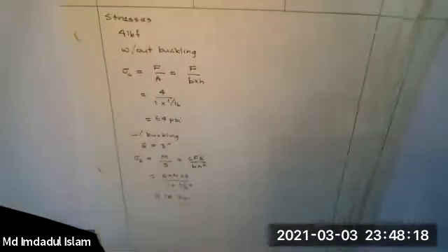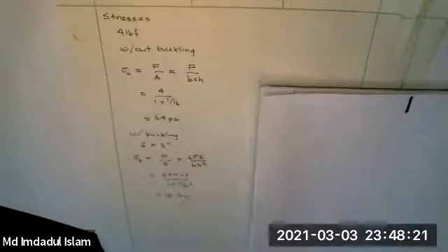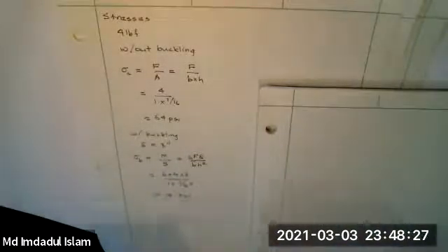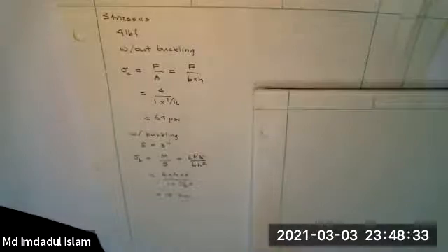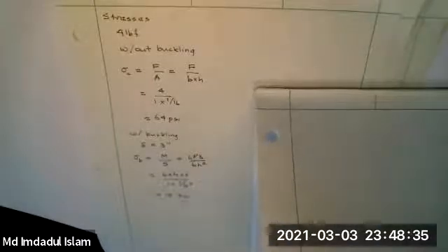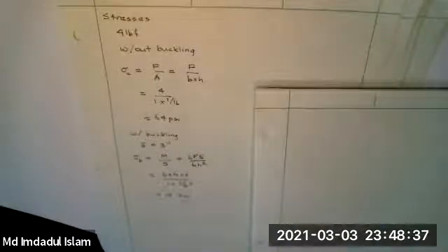Let me do a different situation. We can expect that these buckling loads are going to depend on what you do on the ends. If you let them rotate on both ends, then that'll promote buckling, that'll help buckling. If we clamp them at both ends, that would inhibit buckling. Well, why don't we just clamp it at one end and see what wins?